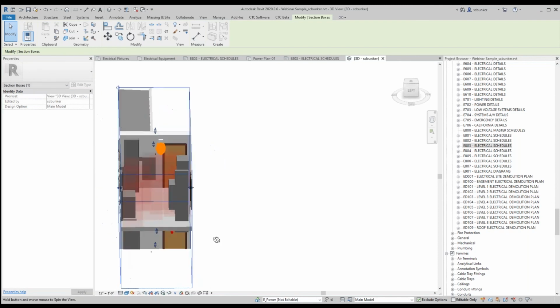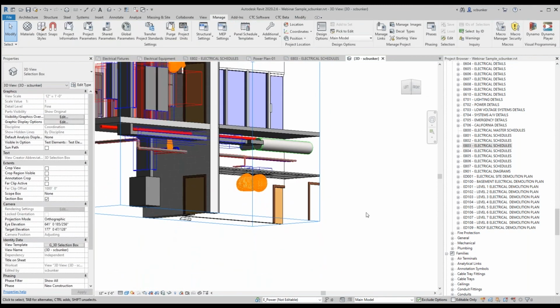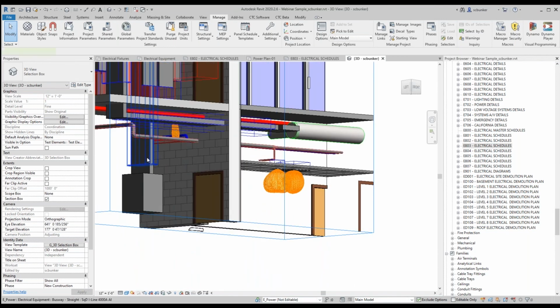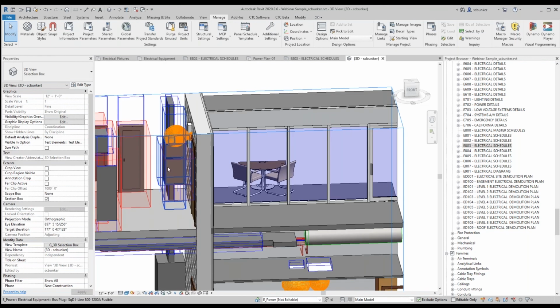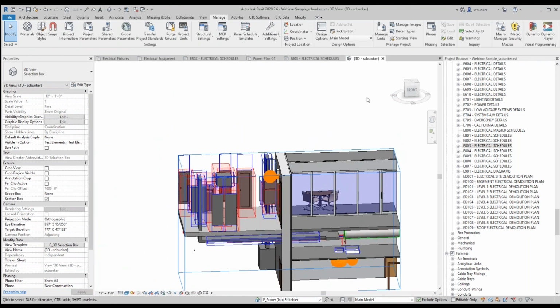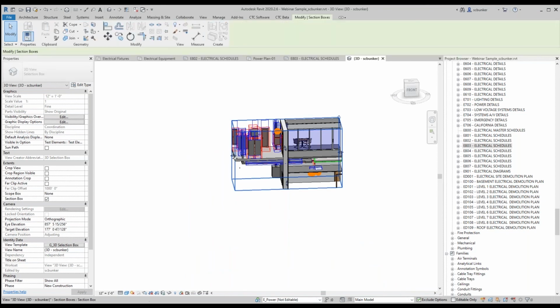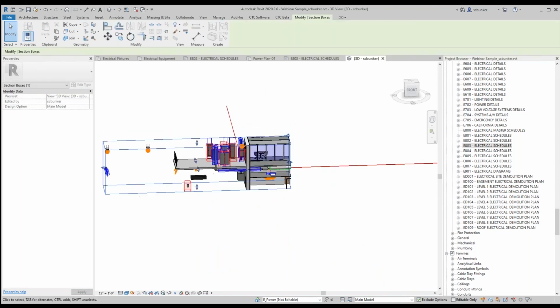Cut out this wall. Here's another one, but this is a tap box. So if you were taking your conduit underground from the switchboard and coming up into the tap box, there's your tap box, and then your busway's on the tap box, and then your bus plug is on the busway there. There are more features about busways than that, but we're running out of time. Let me show you just real quick the horizontal.